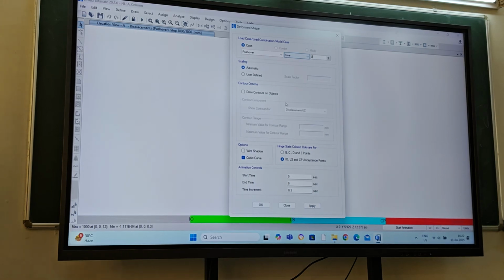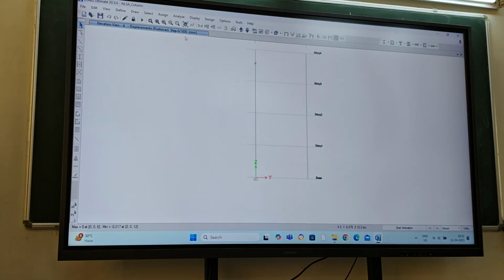We'll start from 0. And here you can observe the steps. Okay. So now this is 0. If I click on this, now it is the first step, and here you see a little bit of deformation. Then second, third, fourth, like that. If you go, you have to cross 1000 steps. And let's see at what step each hinge forms. See how it is deforming. It starts deformation from top, then slowly goes down, reaches the bottom.